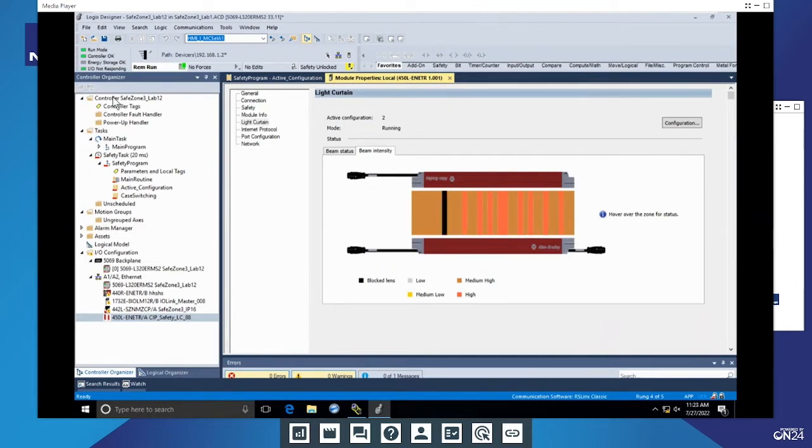Why is this, you might ask? We must have the ability to amend your standard task. We can have timing changes, parameter changes, and device changes. Maybe we're moving from a standard photoelectric device to an IO-Link device. Then we'd have to change our standard parameters. This happens more frequently. Safety, on the other hand, once we've done our risk assessments and established our system, we should not change it. Changing it will compromise our safety, and we can't ensure that everything is done.